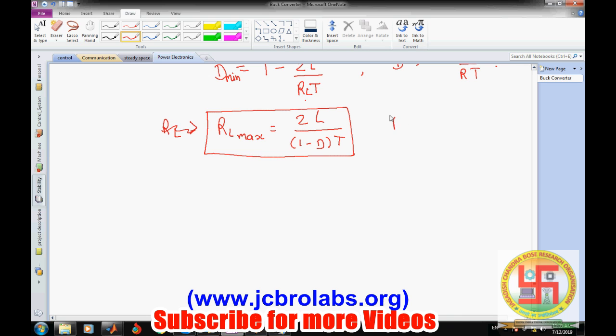If RL goes beyond this RL max, then our converter will go into the discontinuous mode. Then the output voltage will no longer hold the relation of duty cycle to the input voltage. We will also see this through the simulation. So suppose we have designed this buck converter with specific values of L and C. Then we have to provide this much load resistance at maximum for continuous mode of operation. Otherwise, if we go beyond that load resistance, the buck converter and its output voltage may not work well.